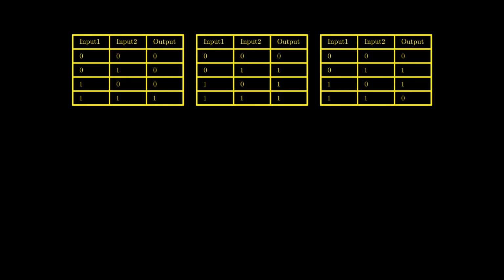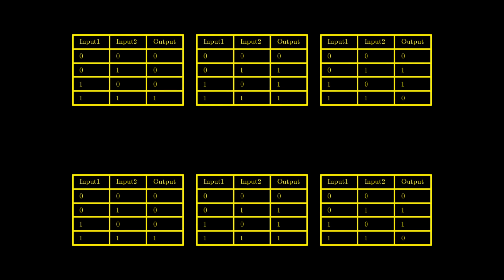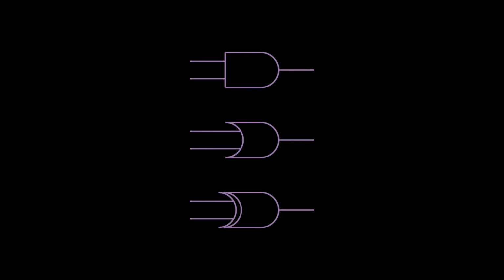We actually have 3 more: NAND, NOR, and XNOR. The N in these gates stands for NOT. Essentially, this is how we can represent these gates. All we do is invert the output of the respective gates to give the output of these new logic gates. Drawing a NOT gate after every logic gate can be quite a pain though, so we're going to shorten it. Remember that circle I mentioned earlier? That circle means to invert the signal. Using that, we instead get these symbols.